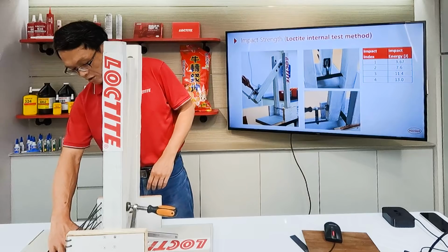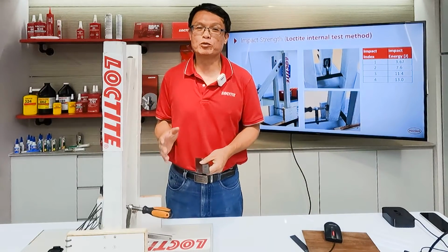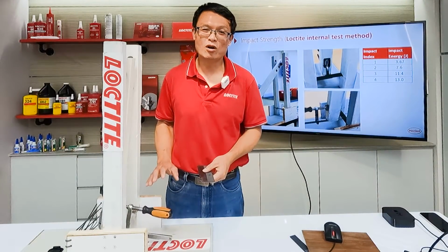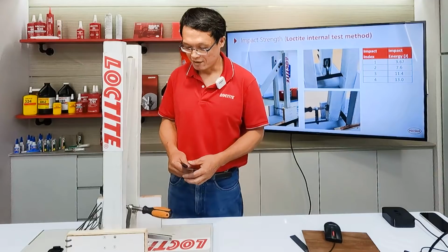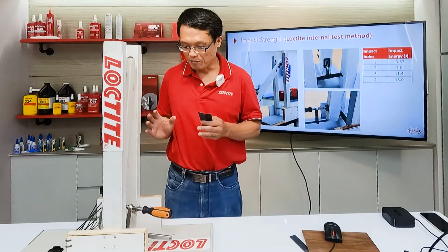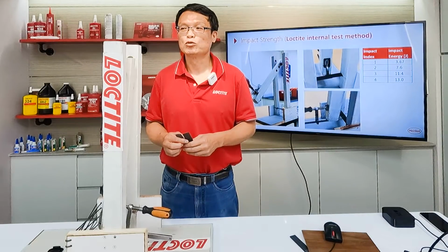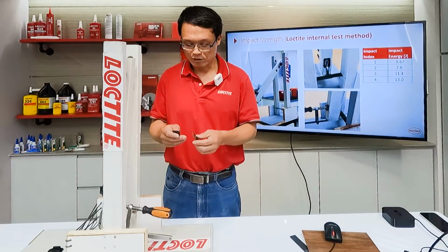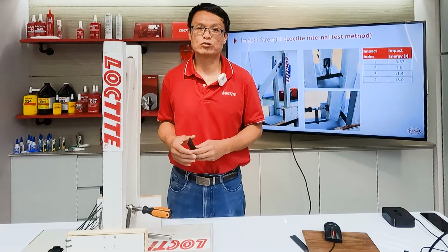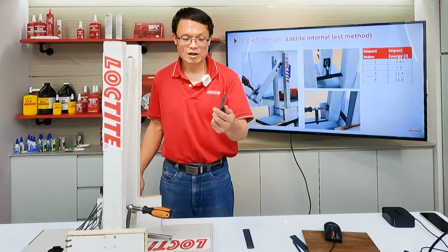Okay, so it breaks, and please understand that maybe some people will say that this is only 3.6 joule, which is quite a small impact energy. But we have to understand the impact time is less than 0.1 second. So the impact delivers a very significant energy in a very short period of time to break the joint. So actually the energy needed to break the joint is quite small compared with static strength.